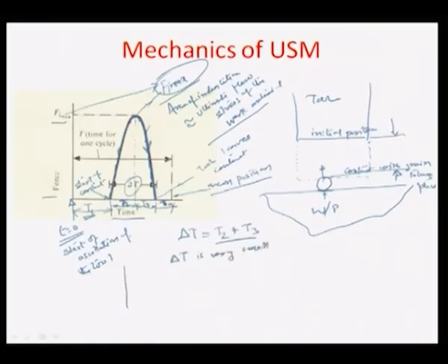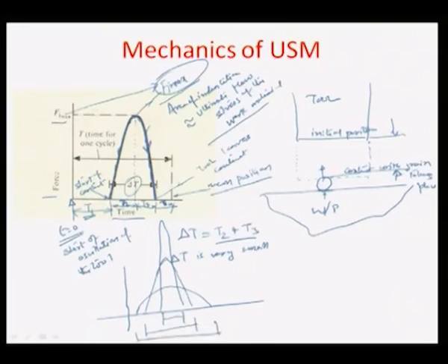And it is obvious to assume that in this kind of situation, with different time values, as you can see here, the curve goes from a round shape all the way to the shape of a triangle, right. So, if this time gap delta t is very, very small, then the force is pretty high, because it is an impact force which creates the stress.